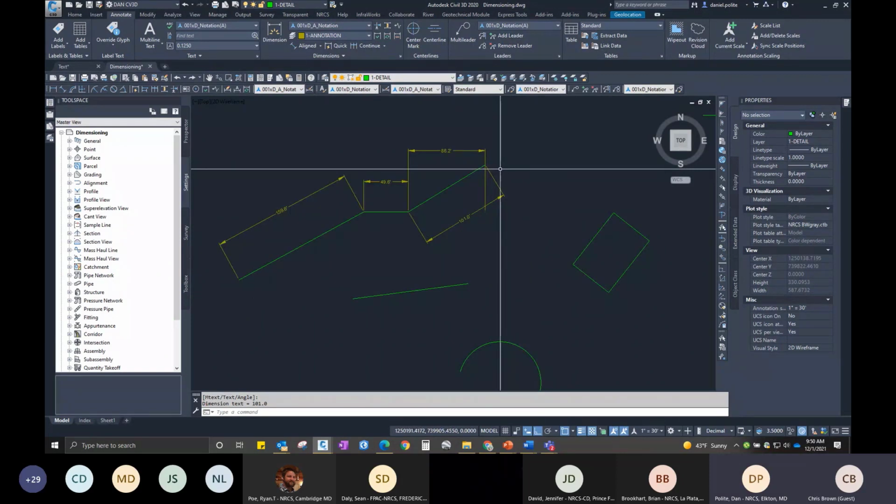So keep in mind when you're doing dimensioning, it takes in consideration that you're in that 2D plane when you're drawing it. Now, when you do profiles and cross sections and things like that, and you do horizontal dimensioning, it will be true to that horizontal dimensioning, because the horizontal is true compared to the vertical exaggeration.